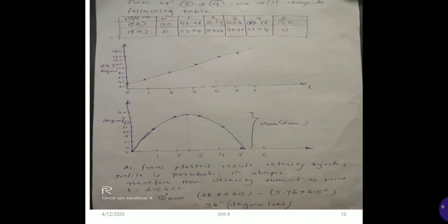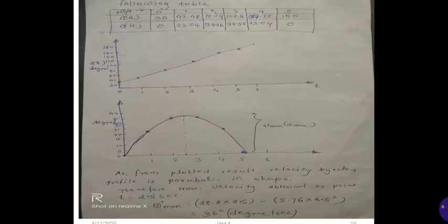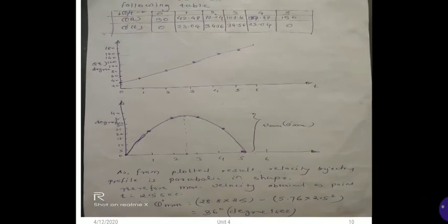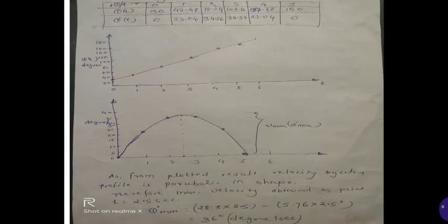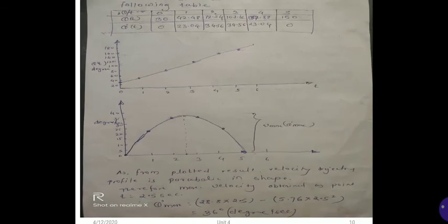Whatever assumptions we have made, that the initial and final velocities are zero, can now be verified after plotting the graph, and we can say that the joint angle and the velocity that we have defined are correct. So in such a numerical, you have one cross check point. Whenever you are solving for the values of theta of t, if the values of theta at 0 and theta at f match the given values 30 and 150, then your calculated values are correct.